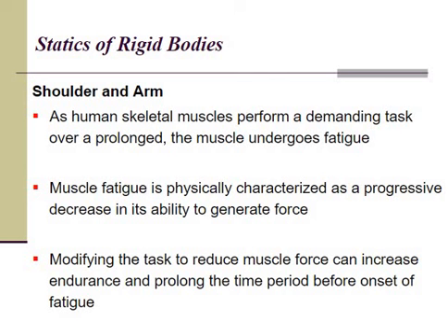When the muscle gets tired, it will not be able to generate this resistance force. So it's our job in ergonomics or human factors engineering to modify the tasks in order to reduce the force exerted by the muscles. By doing that, the muscle can carry loads for a longer period of time before getting fatigued.